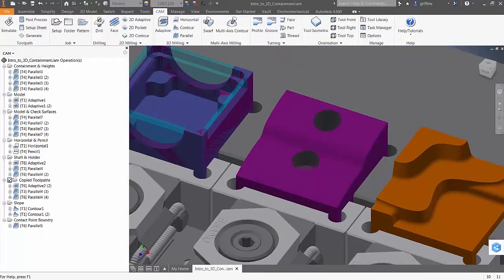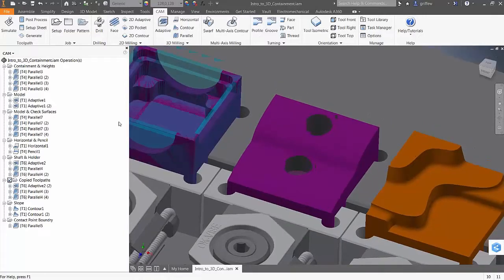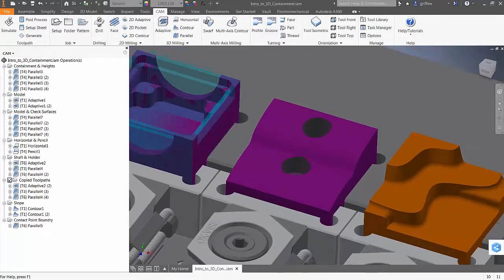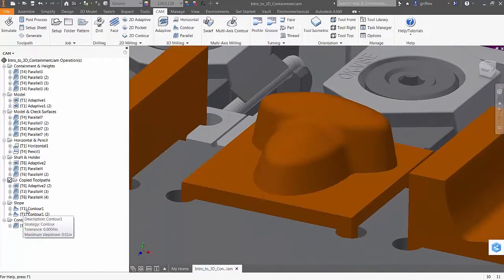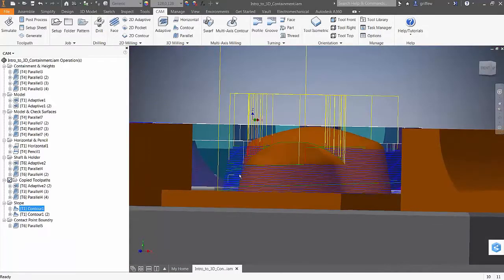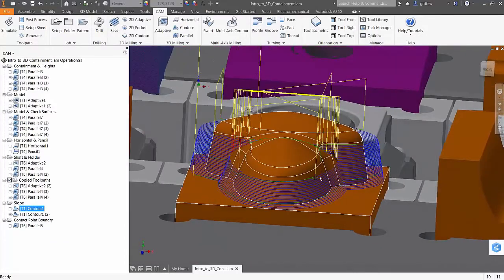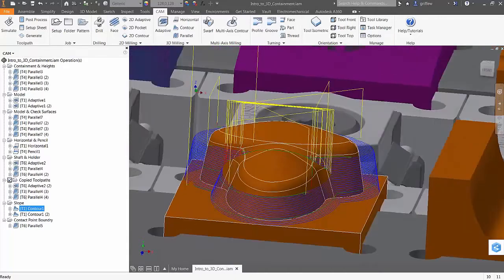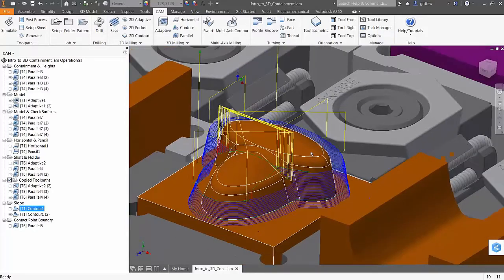Okay, got another question going there. Okay, it looks like Ben is asking. No worries, Neil. So Ben is asking a question, what's the difference between ramp and a contour? So a contour, when you're working with a contour, it'll go around the model but stay at one level. In other words, it'll go around in your Z and then step down, come back into the part and go into the Z. Now, when you're working with a ramp, it's a constant engagement around the material.